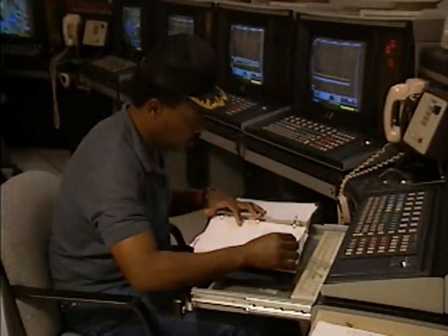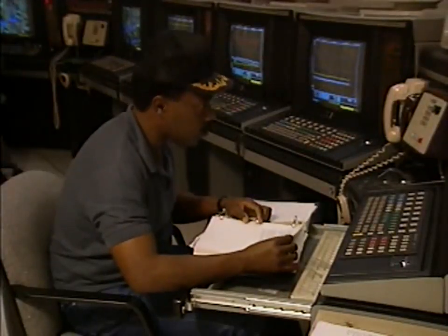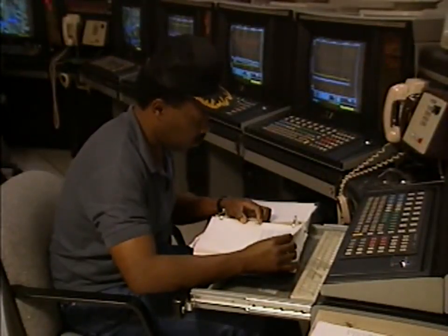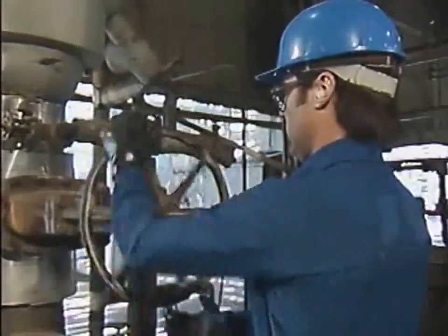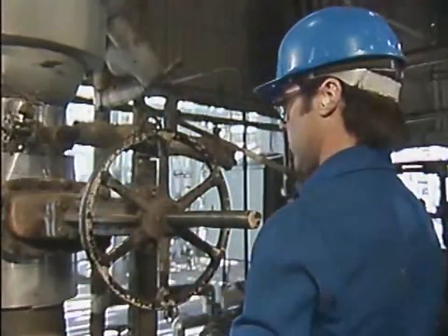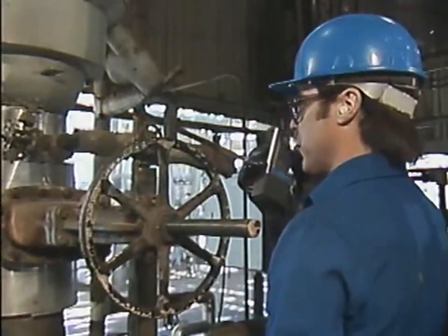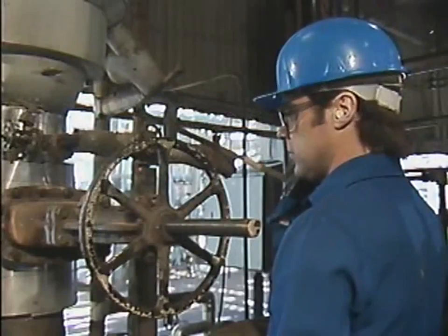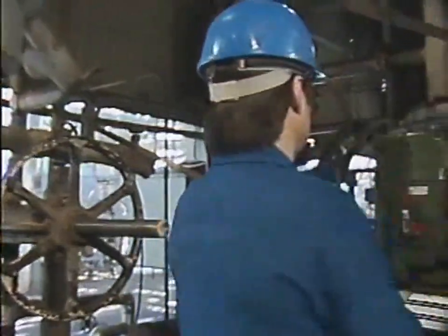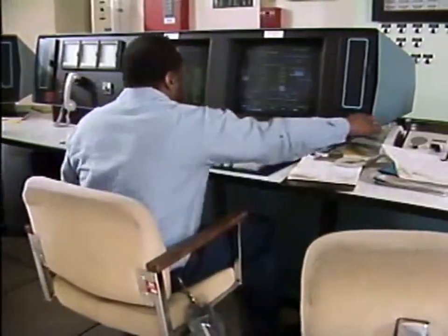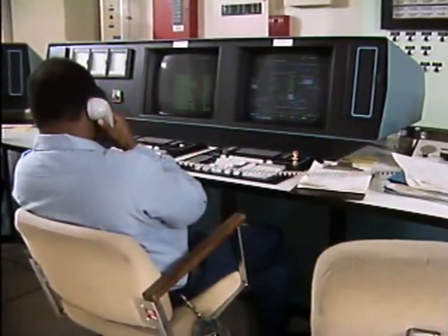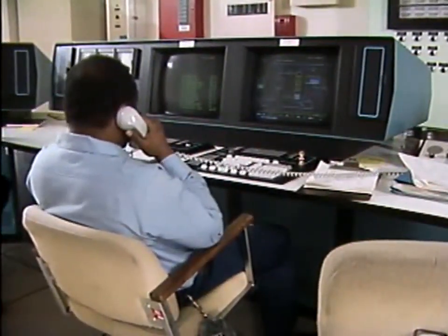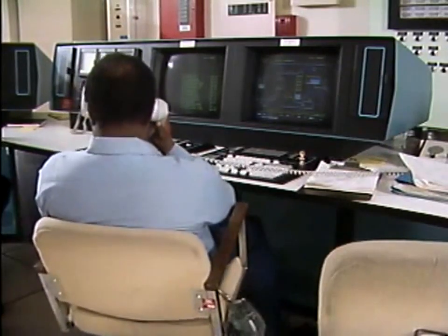When a critical speed is reached, the ramp rate is usually increased to pass through the critical speed as quickly as possible. This action limits the time the compressor is operated at the critical speed and helps prevent damage caused by vibration. After the critical speed is passed, the normal ramp rate is resumed. Some compressors have computer-based control systems. These systems often control ramp rates and make changes as needed to pass through critical speeds.